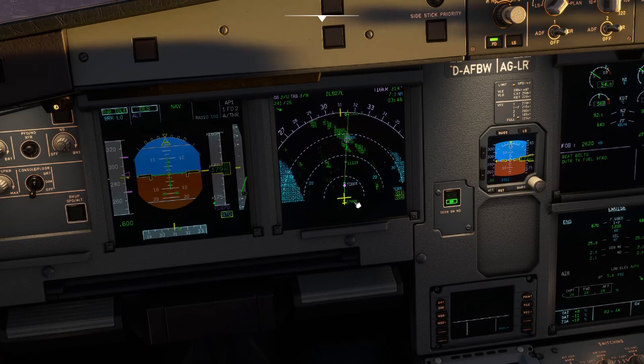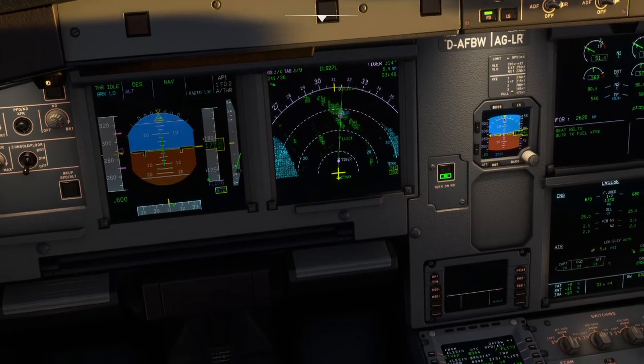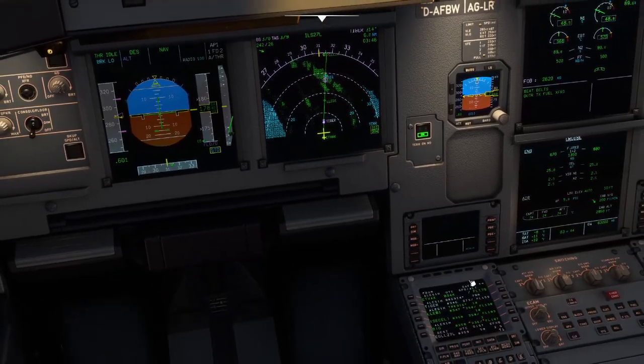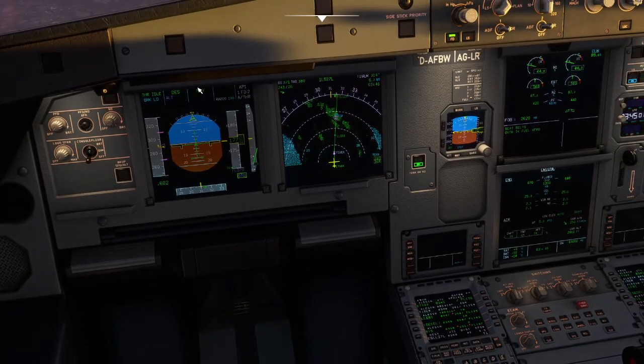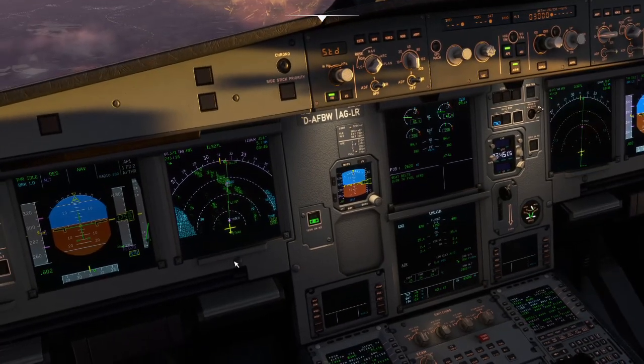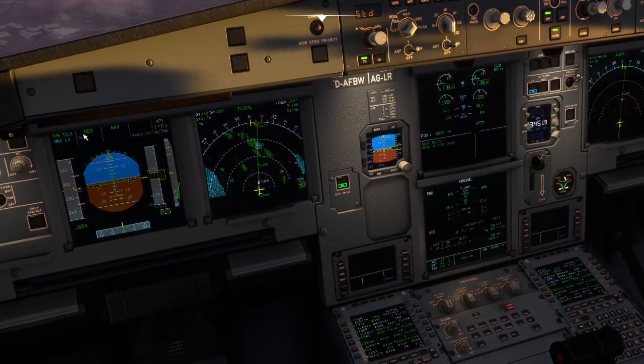That'll be a glitch in either the FlyByWire A320 or just the way it's modelling the current AIRAC cycle of what's in the database there. So it tripped into vertical speed mode, which was not going to help us out. To fix that, I just re-engaged the managed profile, and it's just put itself in the best descent it can, trying to catch up from above.